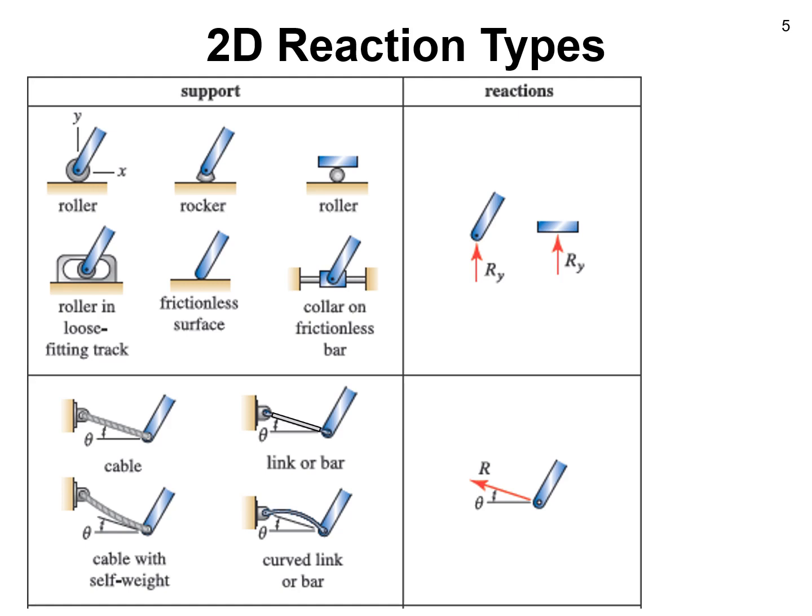definitely would impede you from moving up and down. So our question about what motion is prevented: the wheel, for example, cannot move through the floor. The other bar, like the blue ones that you see, cannot move through the floor. So they are resisted to move in the vertical direction. But because they're frictionless, or otherwise we assume a wheel with a fully greased bearing, they are designed to move freely horizontally without resistance. So there is nothing to prevent or resist horizontal motion.